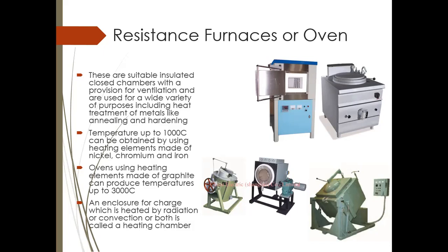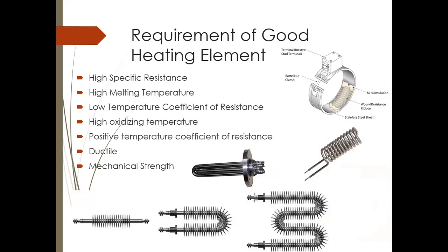With the passage of time, every heating element breaks open and becomes unserviceable. Some of the factors responsible for its failure are the formation of hot spots which shine brighter during operation, oxidization, corrosion, and mechanical failure. So these are the different requirements for good heating elements.